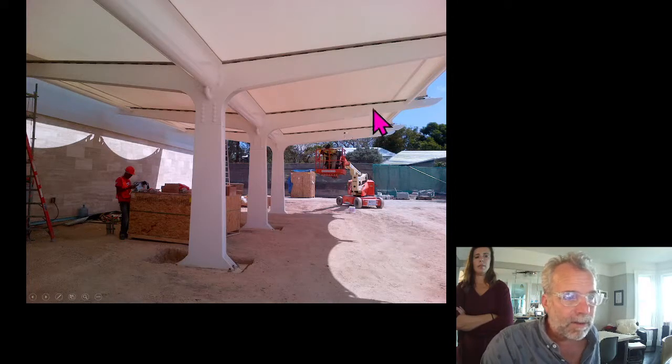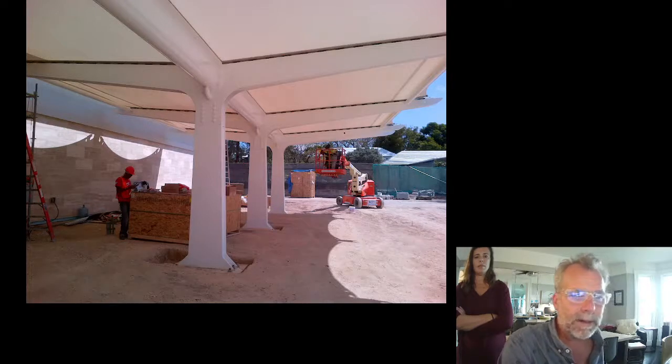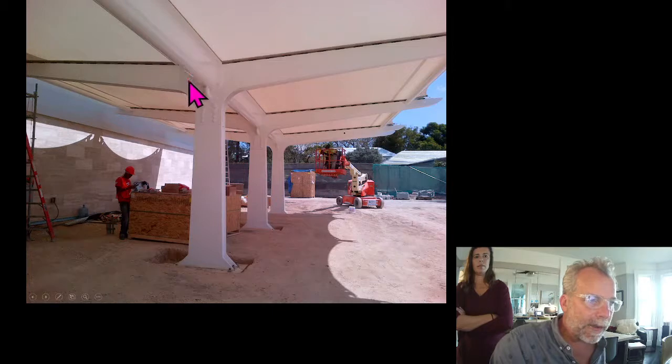This fabric is actually flat, no shape whatsoever, and has stood up to a hurricane with loads sufficiently high that I think our wind loads were 80 pounds a square foot, or about 4 kPa. Typical canopy consideration, this is our gutter.